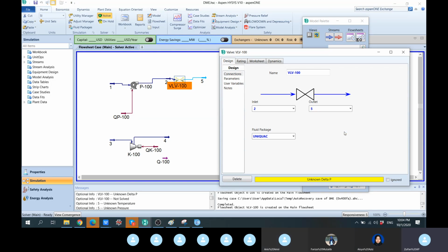So we have one equation, and the flow rate is one variable, CV is another, delta P is another, and specific gravity is another. So we have four variables and one equation, which means we have to specify three variables.